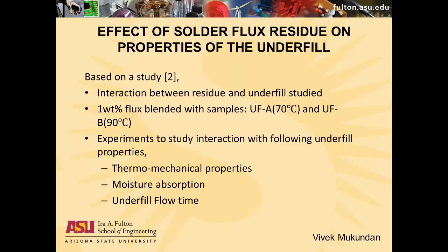Thank you, Jasmin. So I will be talking about the effect of solder flux residue on the properties of the underfill. We followed a study based on this topic, which describes the interaction between the flux residue and the underfill. In an experiment in the study, they blended 2 separate samples of the underfill with the flux, named UFA and UFB, which were dispensed at different temperatures. The properties that are talked about are thermomechanical properties, moisture absorption, and underfill flow time.